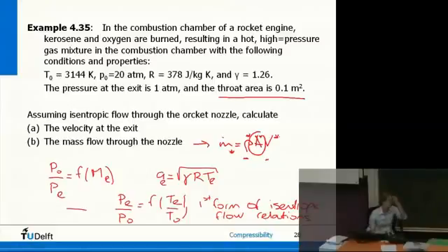Question, why is the Mach equal to 1? Yeah, it's a bit hard to explain. I think later I have a few slides on that. So if you put in the equations, you can see a relation between areas and velocities. I'll do that later. But if you do the computations, you will find it. So Mach is 1 in the throat, always, the smallest cross-section if you have a supersonic nozzle. And this rocket engine looks something like this, with an exit and a very strong contraction ratio. Flow through this combustion chamber. Yeah? So, rho. Who gives me rho?